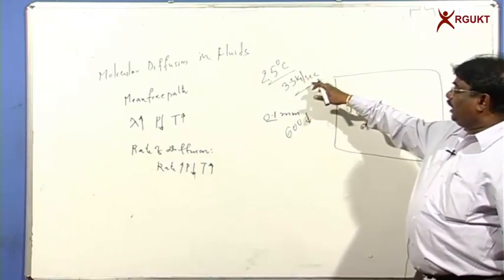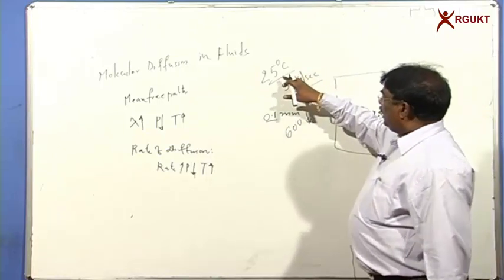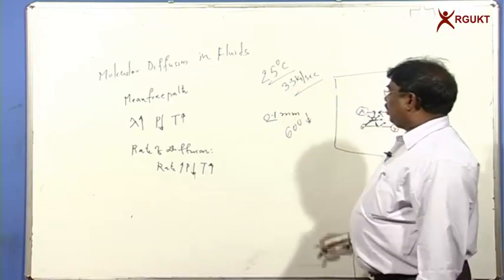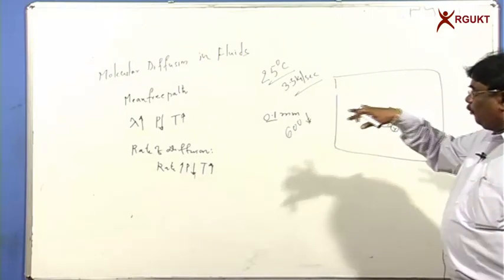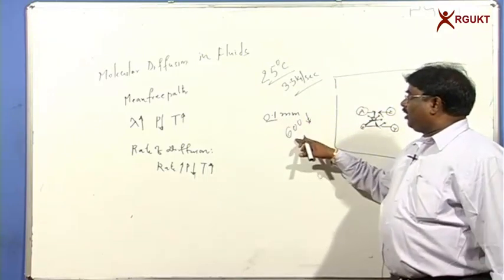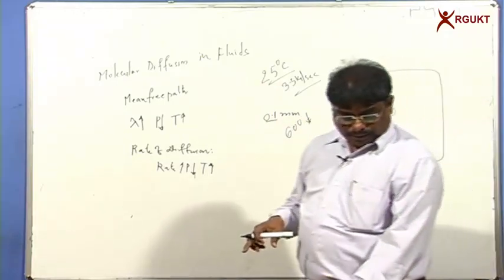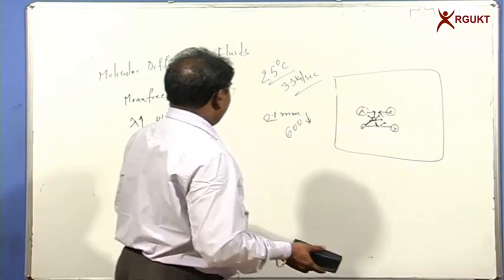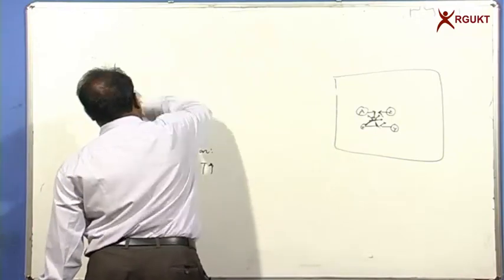What I am trying to tell you is, if you maintain the vacuum at 25 degrees centigrade, the water is evaporating, 3.3 kgs of water every second. Just if you put a stagnant air over the liquid water with a thickness of 0.1 mm, the rate of evaporation of water is decreased by 600 times. So this shows us that molecular diffusions are very, very slow, and they are reduced further by increasing the pressure, and molecular diffusion increases with increasing temperature.